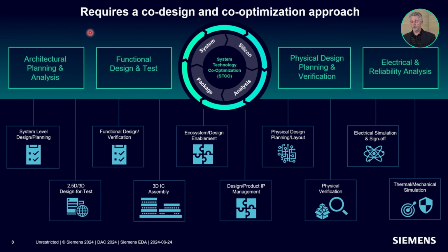So as you're doing your system decomposition, those are factors that may impact which way you architect. Can I get away with a silicon interposer? Do I need to do an organic interposer to keep the cost down? Do I do 2D, 3D? So there's a lot of other non-architectural factors that need to be considered when you're defining how you're going to decompose your system and implement that as a 3D IC.